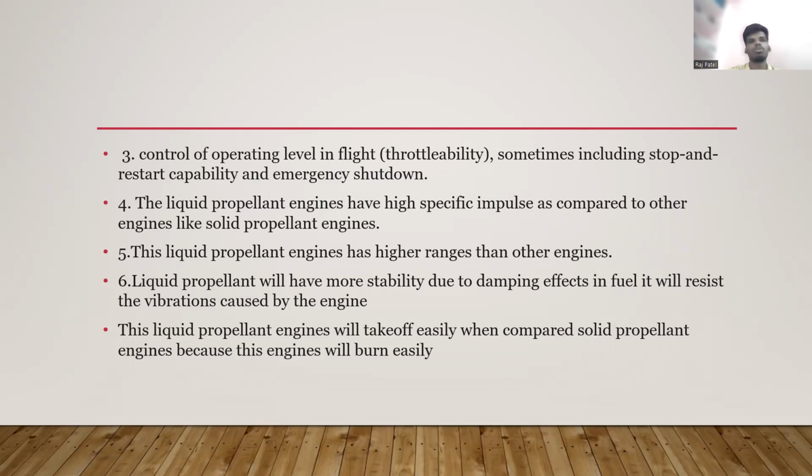Whereas in liquid rocket motors, we can stop the vehicle by turning off the valve of the liquid propellant and oxidizer, and control the flight operations. So this is another benefit and feature of liquid propellant motors.